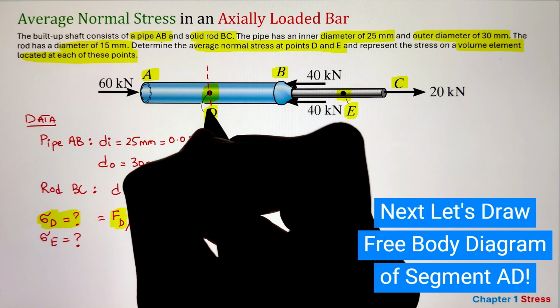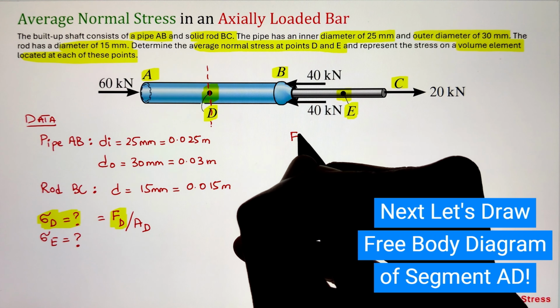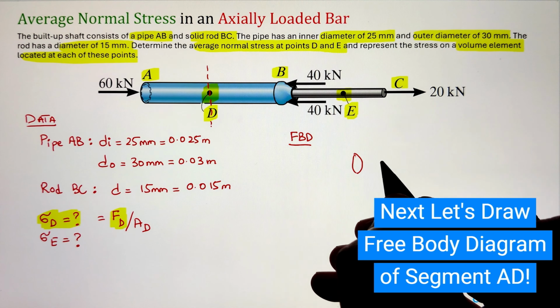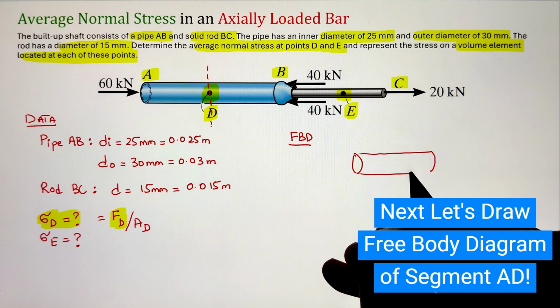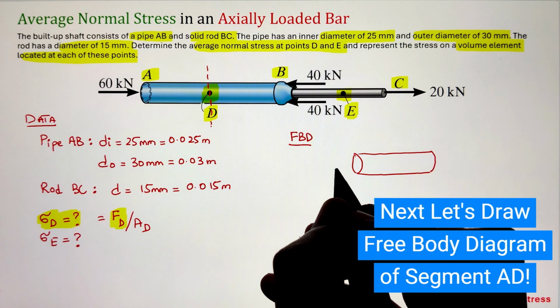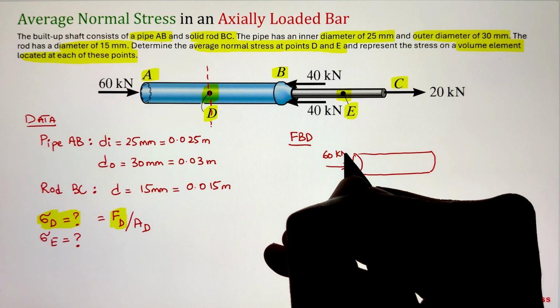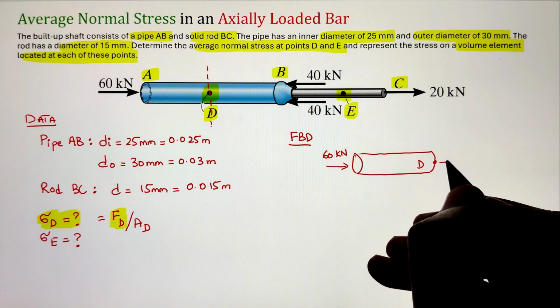body diagram. Now, since we have made a cut at point D, we can select either one of the sides of that section. That is, either I can draw the free body diagram from A to D or from D to C to calculate the force at point D. Since it is easier to solve section A to D, that's why we are going for that.